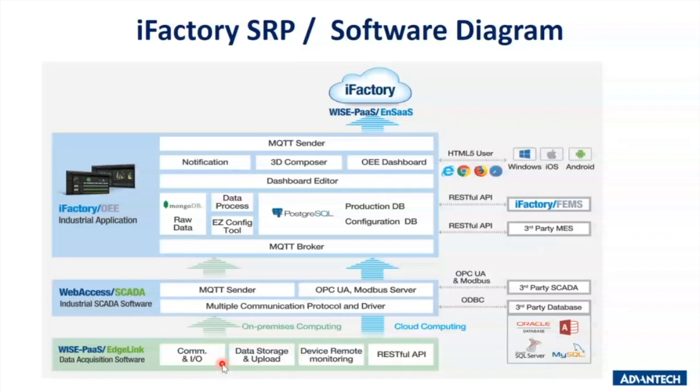As I shared with you, inside there is built-in SCADA software, gateway software. So all the I/O, you will connect the data to our SCADA software. And because our SCADA software supports the open platform, you can actually connect it to a third-party SCADA through the OPC UA connectivity.